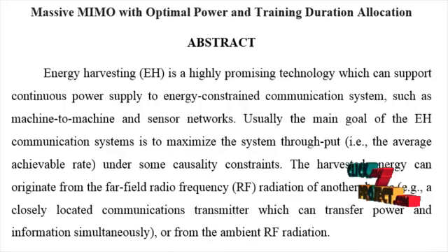Some interference mitigation is offered by limited intercell coordination, which is conventionally restricted to scheduling or user assignment mechanisms, or soft handover techniques. Intercell interference is treated as noise at the receiver side and is handled by resorting to improved point-to-point communication between the base station and the mobile station using efficient coding or single-link multiple antenna techniques. Optimal precoding over the broadcast MIMO channel as well as optimal joint decoding over the uplink involve non-linear computationally intensive operations which scale poorly with the size of the network.